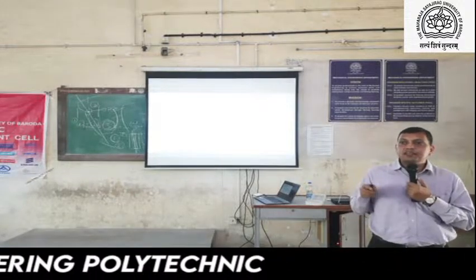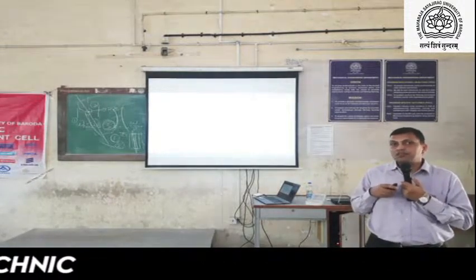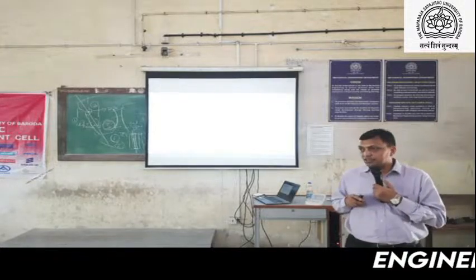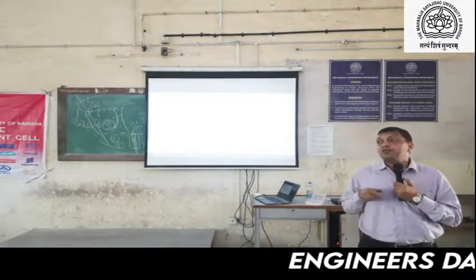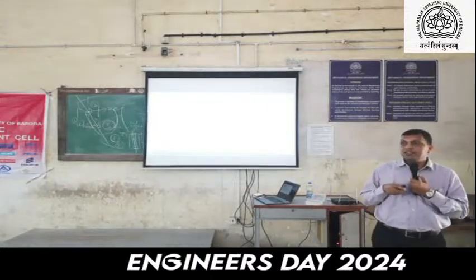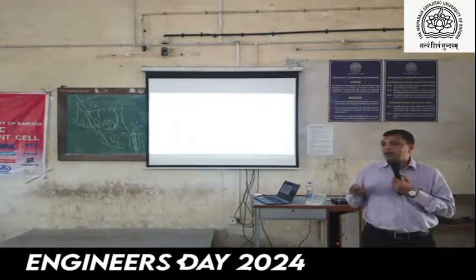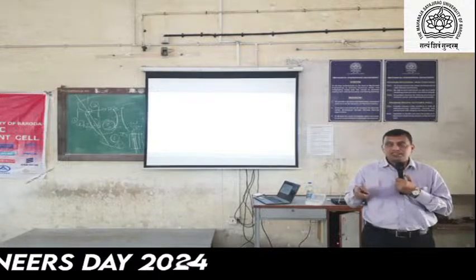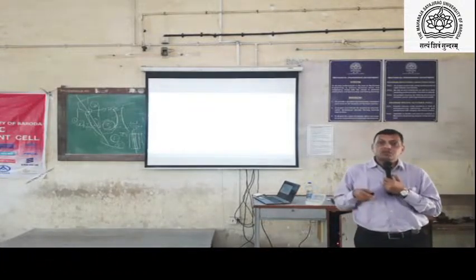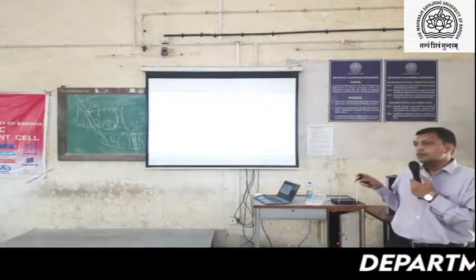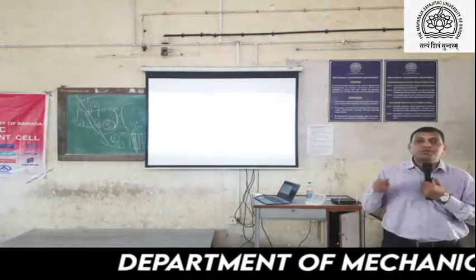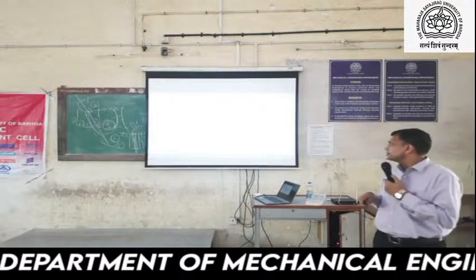If we directly define that in 1 minute the peak load lasts only 10 seconds, and we consider the full 60 seconds for our design, then the design will be higher, safer, and costly. So in that case, we have to consider the particular behavior of the cycle, and based on that we can optimize the selection.